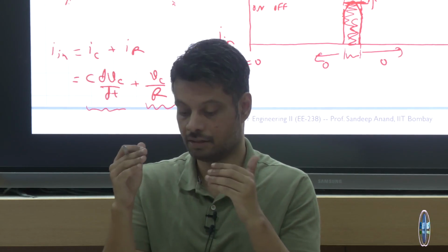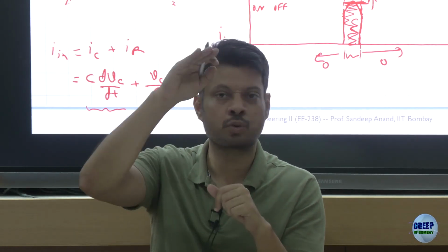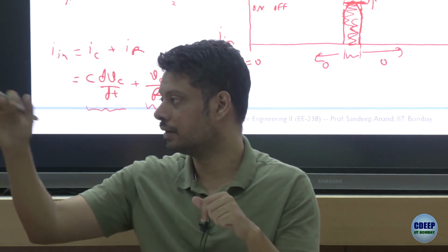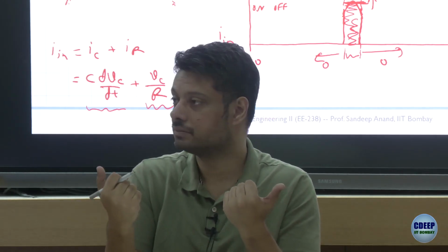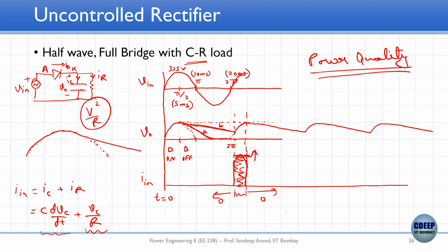If you had a capacitor, it is almost going to remain at the peak with a small ripple. So your average will be very close to 325, slightly less than 325, right? So the output average, this is the symbol I would use for average quite frequently, is very close to 325 volt, maybe a little less than 325 volt, in this case.